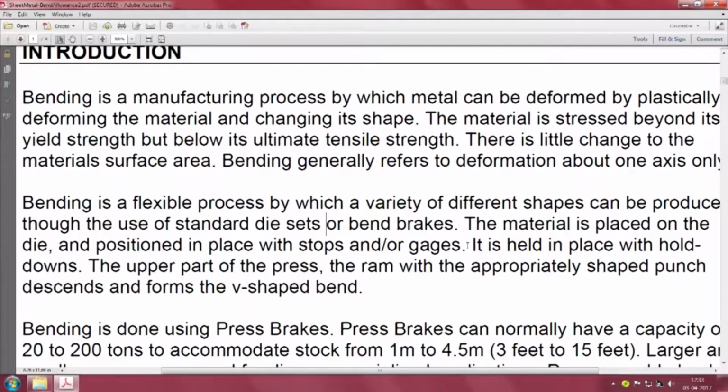In the case of mass production, it is not worthwhile marking every sheet. So, instead one sheet is marked, and at the back a stopper is put. That stopper will ensure that next time you need not mark it again. So, maybe 100 pieces can be done, you just feed it into the area of operation and keep doing.